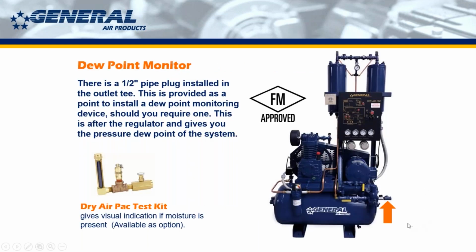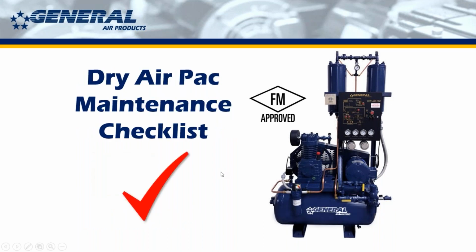On the outlet of the compressor, this is another thing on the dry air units. To make sure the dry air unit is working and it is in fact dry, you put on this dry air pack test kit with a color change desiccant on it. And when the color changes, that means moist air is coming out of the unit, which means you need a desiccant change, which is one of the big differences in what you need to do with the dry air pack. So we'll talk about that now.